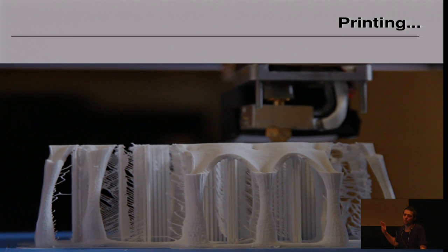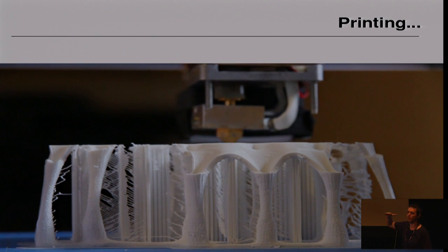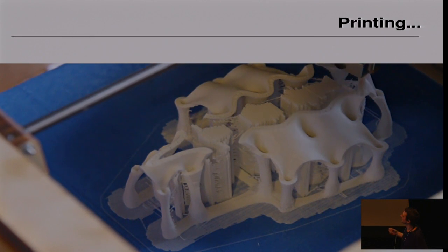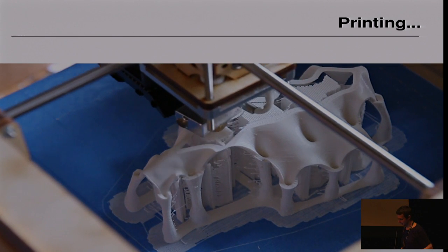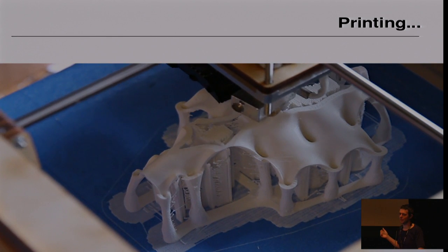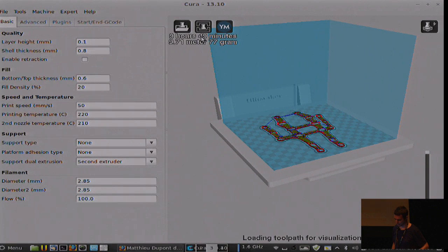So here I was afraid to print it without the support that allowed the horizontal part to have some support, but I think I could have printed it without support. So we can see that sometimes you will need some work to polish and finish the piece. This printing took, I think, something like 15 hours to print. So it can be very, very long. The problem is not the cost of the material, the problem is the time it will take to print.